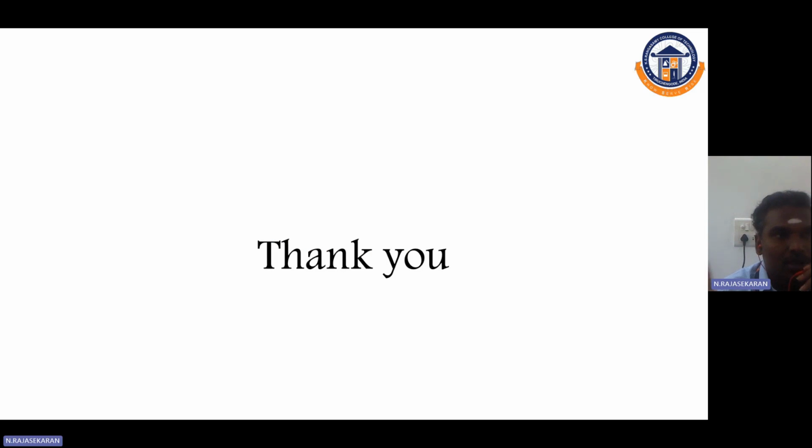So, up to this point, the overview of the presentation: first we discussed the characteristic impedance of the line, two parallel lines, where Z is nothing but square root of L by C. The same characteristic impedance for a lossless system is the surge impedance, which is a very important thing. Based on the inductance and capacitance, we arrive at the surge impedance.